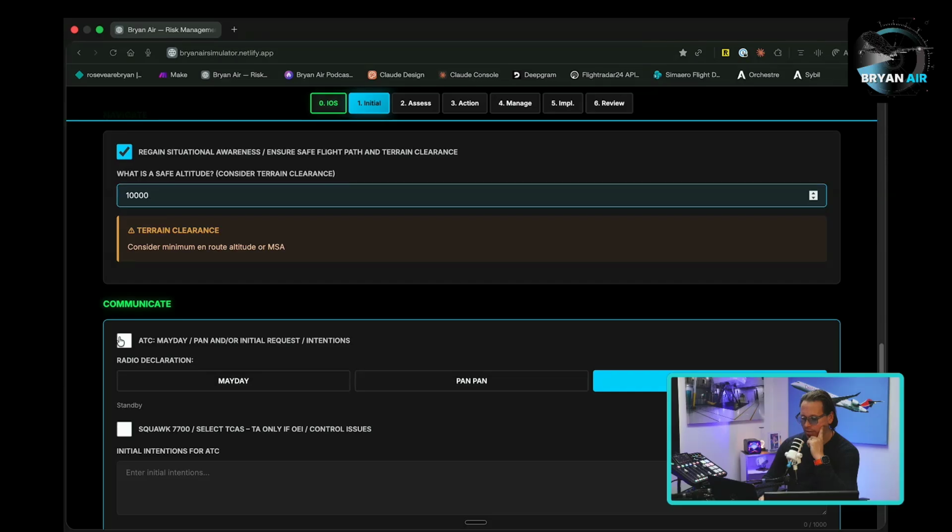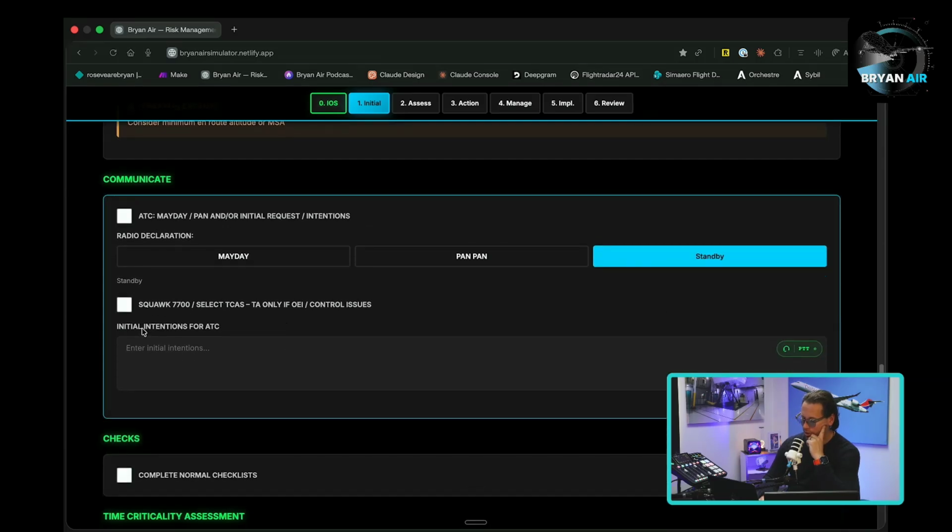So are we going to give a mayday call here? Are we going to give a pan call? Or is it going to be more of, we may not be able to climb to our desired altitude, so just stand by. So I'm going to say stand by, but I'm not going to select a mayday or a pan scenario there. Also, no need to squawk 7700 in this case.